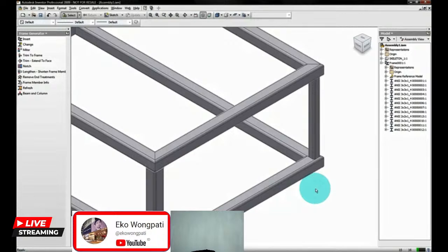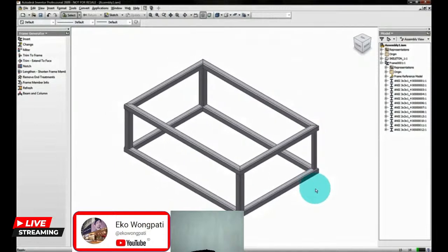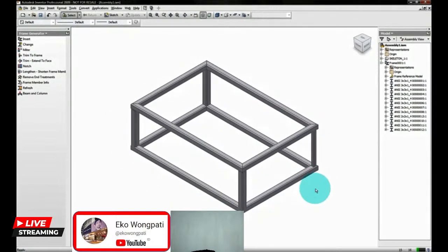So as you can see, we just take a skeleton file, we get it the shape of the frame that we want to create, we bring it and place that skeleton file into an assembly, we save the assembly, go into the frame generator environment, start inserting our parts where they need to be. We can offset those, we can change the orientation if they're outside or inside or with an offset of set dimension, get those where we want, apply the end treatments, and we have our frame.